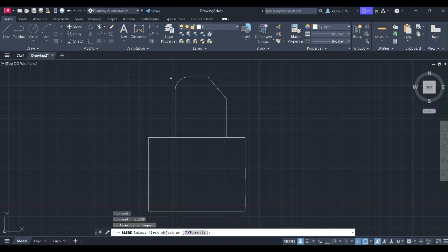If you don't want any chamfer or like that, you can create your own. You have to first specify or select the objects. So I am selecting this, and then select the second object. So this is the blend curve created. In this case, it is created in an awkward way. If you want to make an actual drawing, it will look good. So these options are clear.